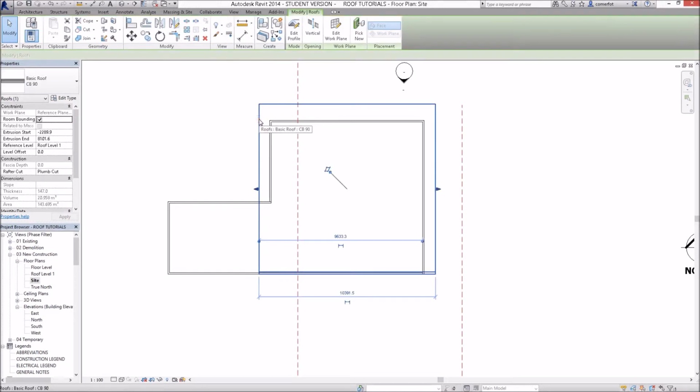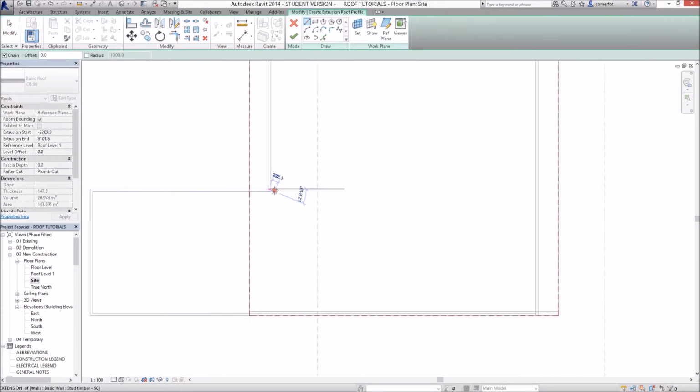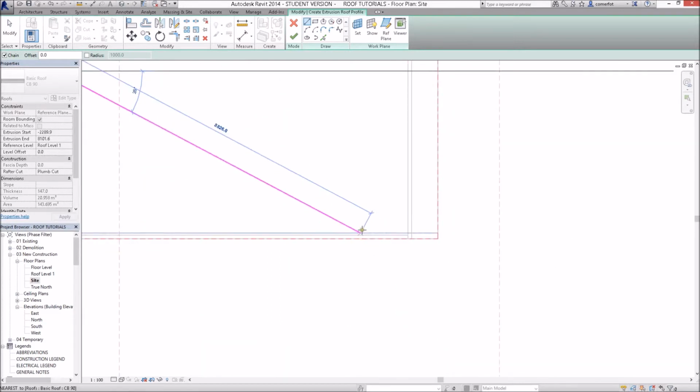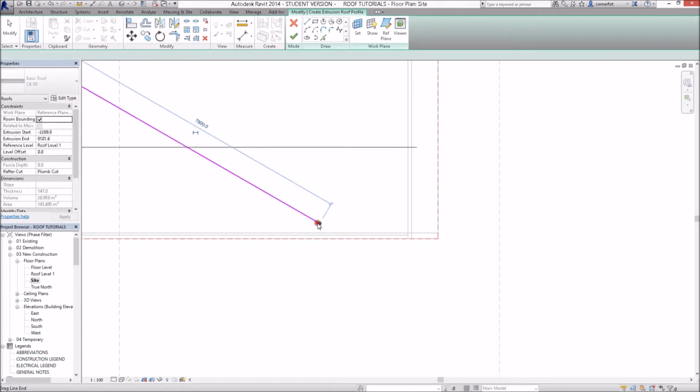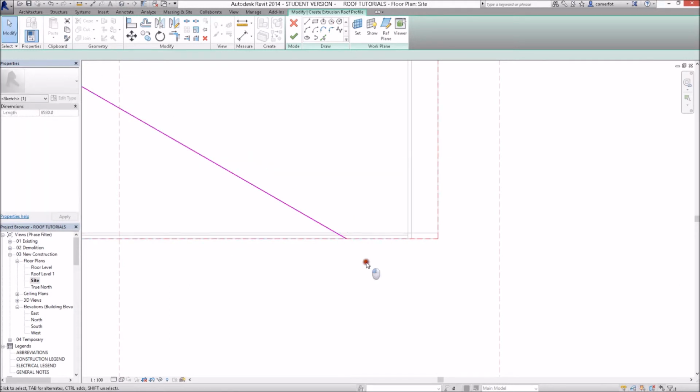But if I select that roof, what you can do is create an opening in that roof, and this particular tool that's available to us, roof by extrusion, it'll create a vertical opening straight through that roof. So I was thinking of creating a sketch shape, something like this. I'll come down at 30 degrees or something. Yeah, that'll do. Come out 30 degrees. Yeah. And then I'll extend that out on original till it hits the edge of the roof,